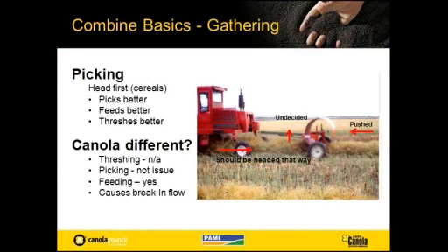I'd mentioned before that the roller plays an important role in which way the canola windrow actually is laid. Now, normally we always follow the windrower in the same direction with the combine, because that would normally give us head first feeding. What we find is that a lot of time in heavier crops, where the material comes out from under the windrow, more or less standing or slightly laid the way it normally would be, gets hit by the roller, and the roller, instead of just pushing it down, may actually push it forward in the same direction.